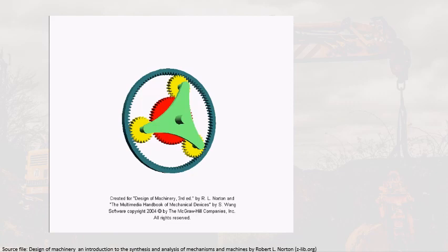So it can easily be tapped as the output member. Most planetary gear trains will be arranged with a ring gear to bring the planetary motion back to a grounded pivot. Take note that the sun gear, ring gear, and the arm are all brought out as a concentric hollow shaft so that each of them can rotate.